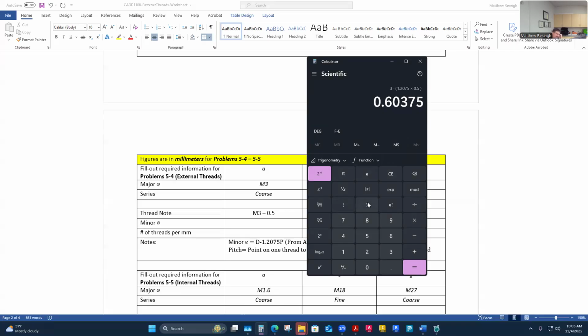And obviously it should be less than 3 millimeters because I've got to be able to cut threads with it. It's going to be 2.39, so I'll probably just go to 2.4 on this. I don't know what I did on my actual answer sheet, but I carried that to 4 decimal places, 2.3963, I guess is what I'll write here.